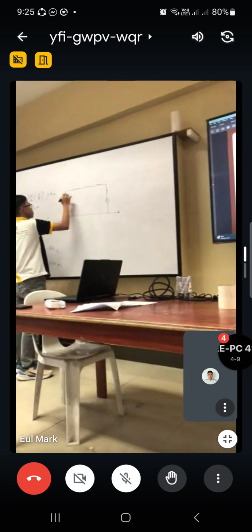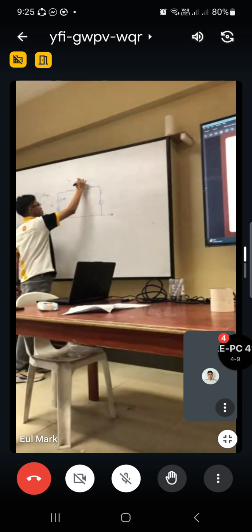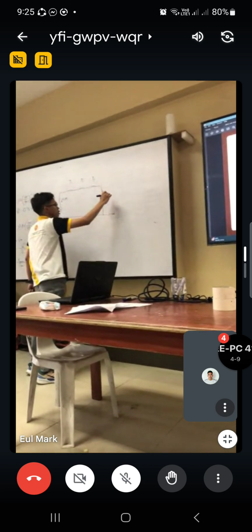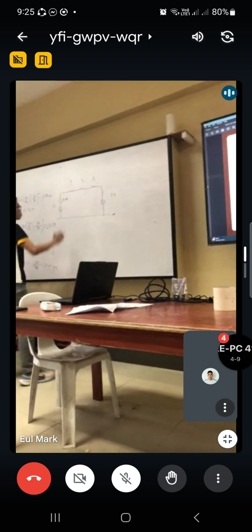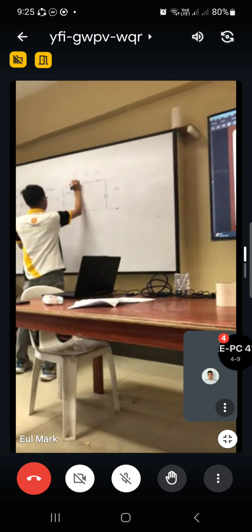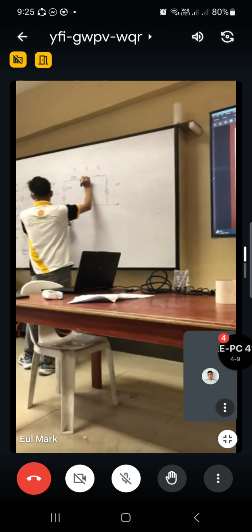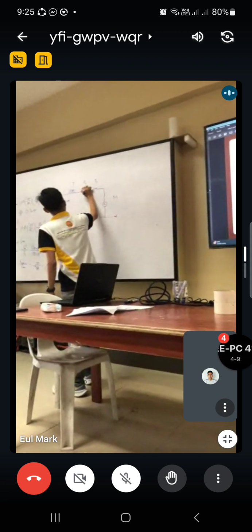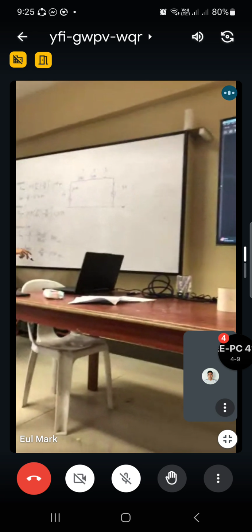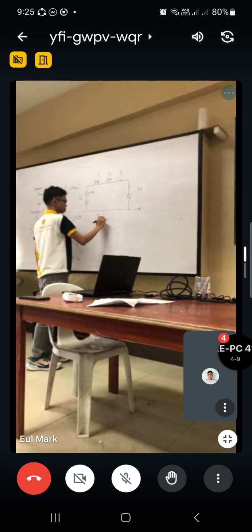So here is G1, this is P1, this is the transmission line, P2, this is the motor. So this is j0.0375. The transmission line is j0.103. And then, of course, you solve for transformer 2.